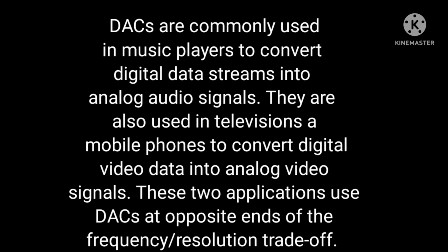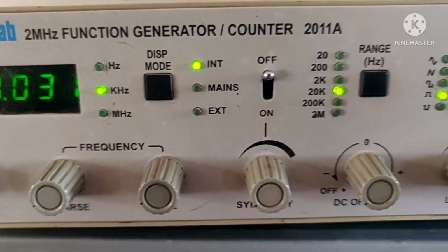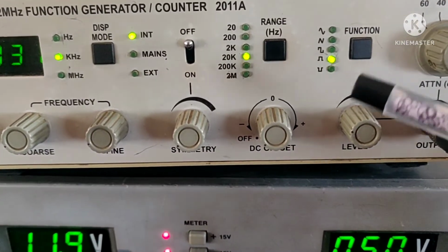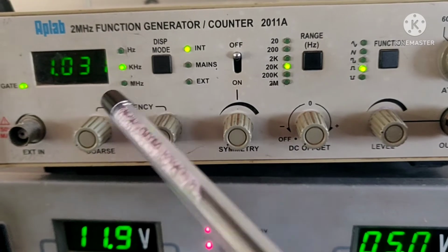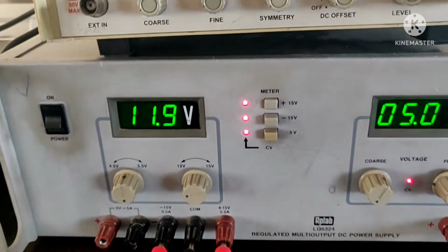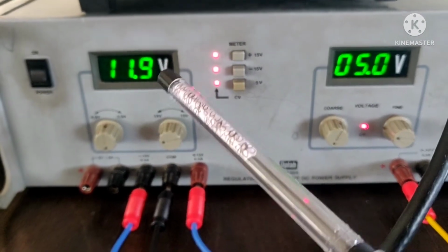Every time you have to understand the applications of that, and before that you have to see the settings to be done in the function generator, because we are going to generate the staircase at a frequency of 1 kilohertz. Adjust the frequency to 1 kilohertz and select the range, select the function key for pulse or square waveform, and adjust the amplitude to 5 volts peak to peak. This is the initial stage you have to set. After that connect plus or minus 12 volts for the op-amp's power supply and 5 volts for the data input.